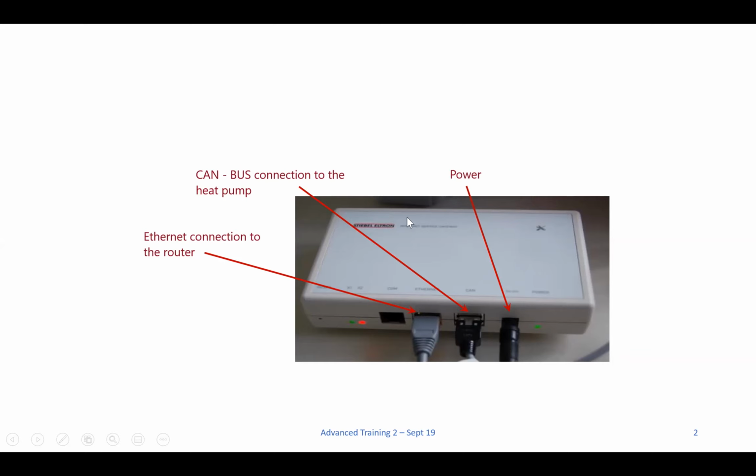normally speaking, the WPM is installed in the plant area near the heat pump manager, and a double power point is installed there, and an Ethernet port is installed there next to where the ISG is going to be. And the patch cord that we provide plugs from the ISG into the Ethernet. Now, you'll see an LED over here, on the right-hand side, which is the power indicator. So when that's green, it means the power's on.